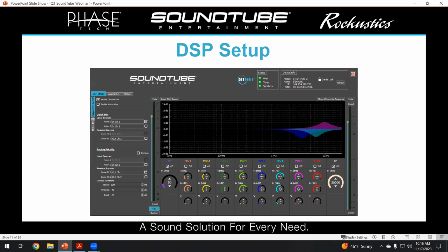So if it's a true 4 ohm load, it will work, but your output will be lowered. You won't get as much level out of it. If it is a load that drops below 4 ohms, then Mike's correct, it will overcurrent and the PoE port will drop out.